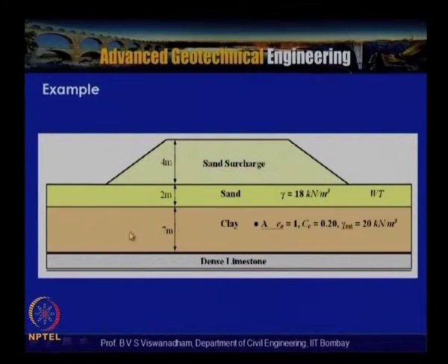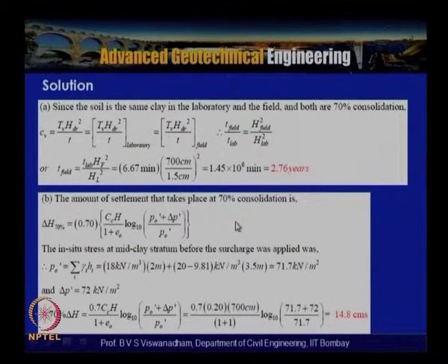So, here also we can look into that if you divide the clay into a number of small incremental thicknesses, let us say 1 meter, 1 meter, 1 meter, then for each thickness, if the settlement is delta 1, delta 2, delta 3, like that up to delta 7, then what we need to do is calculate the increase in load due to the so-called trapezium load. That is, if you use the method of superposition, I can use this triangular load and this trapezium loading, then we can get the settlement at this particular point. With that, we may get a more accurate estimation of the settlement.